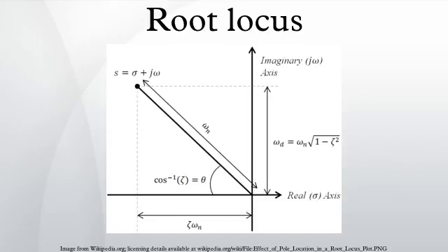Many other interesting and relevant mapping properties can be described, not least that Z-plane controllers, having the property that they may be directly implemented from the Z-plane transfer function, can be imagined graphically on a Z-plane plot of the open-loop transfer function, and immediately analyzed utilizing root locus. Since root locus is a graphical angle technique, root locus rules work the same in the Z and S planes.